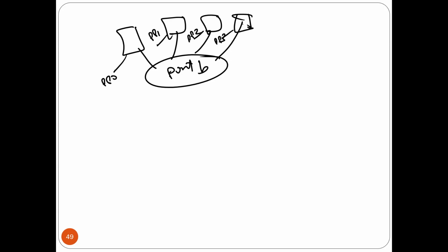Okay, so if you put here the code of number 7, for example, and all of them are enabled, you are going to see 7, 7, 7, 7. For sure, that doesn't make sense, right? So I don't want to repeat the number, right? That's why we don't use it this way. So again, the technique is called time multiplexing. And you will understand from the English word why it's called time multiplexing, simply because we do multiplexing in time, as you will see right now.